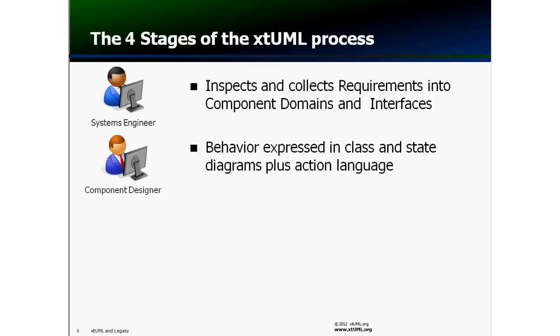These then are delivered to the component engineer, the component designer, and often there are multiple components in the top level system diagram, and individual components will then be allocated not only to design engineers but possibly design teams, and possibly those design teams are building models that will ultimately be implemented in different technologies, such as embedded C code for one component, VHDL AMS for another component, maybe System C for another component. This system level model can be broken down and allocated by team and by technology.